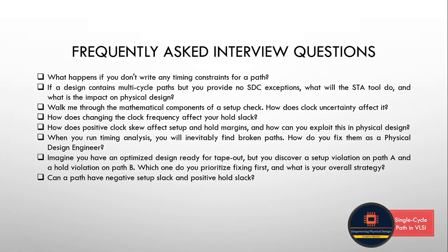Okay, so that's why we must provide an SDC exception. We must provide an SDC file where we properly define all the constraints. Otherwise, it will affect things one way or another, because if we are not defining any exceptions or any constraints, the tool will by default take it as a single cycle.